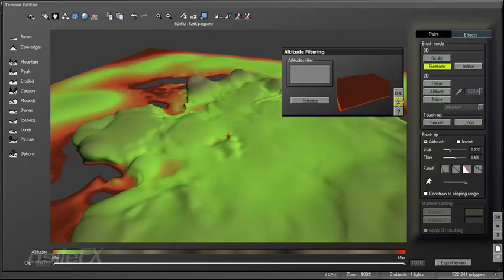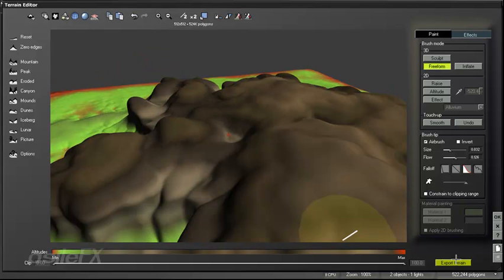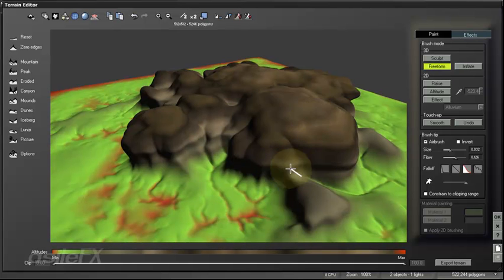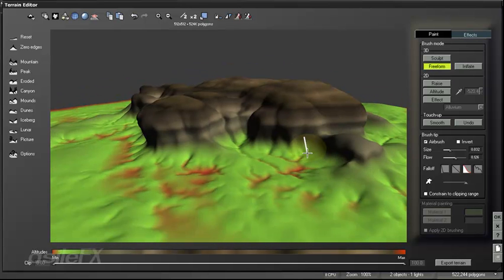So if you wanted to clean up the displacement layer only so that it doesn't have as drastic of an impact or cause any issues, because sometimes you'll see overlapping geometry within the displacement layer but not in the full geometry, you can export out the terrain, and I cover this more in the next lessons where I show the breakdown of each layer.